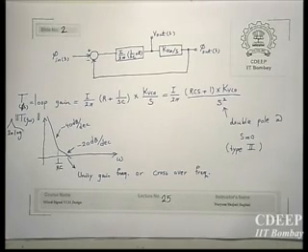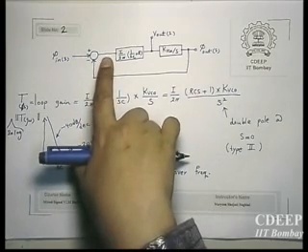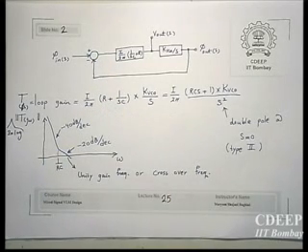So eventually, this is one of the good properties of the PLL loop. It doesn't really oscillate at those frequencies, because at very low frequencies the two phases at the input of the charge pump will be almost equal, so you don't get any signal. The output of this phase difference will be 0. That's why your charge pump doesn't work. The loop settles to a steady state and stays there, ideally.